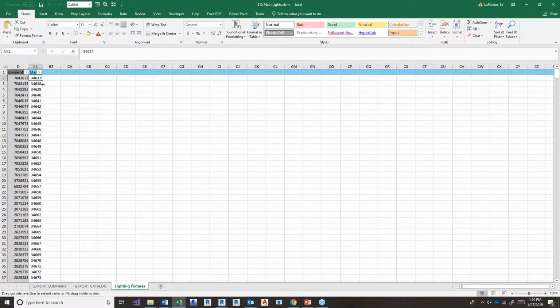Normally under Excel, I might expect to be able to drag and drop a cell and have it auto increment. That's the default functionality, which in the development of BIMrx, we thought was often less appropriate for modifying parameters. Very often we might be dragging and dropping, say it's an equipment tag or it's a lighting fixture ID. We want the next light fixture, if we're dragging LF10, we want the next light fixture to also be LF10. So BIMrx shut off that functionality initially. What that means is if I want to auto increment, I just hold my control key down as I drag.